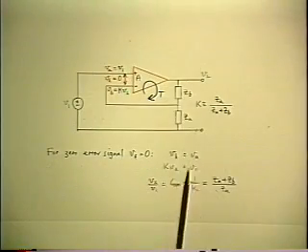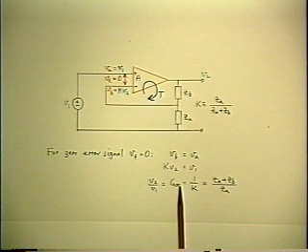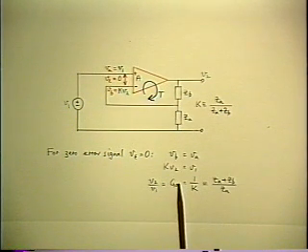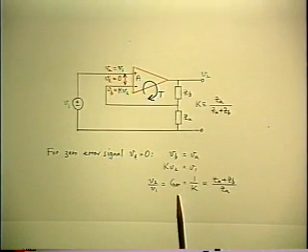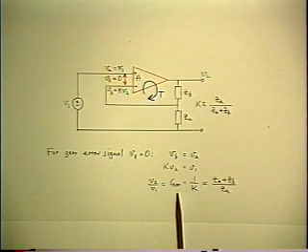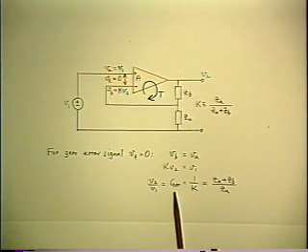And it's the part that usually gets neglected in the design of the system. Because everyone does the part with G infinity, forgetting that it's G infinity and not G, and forgetting to do anything about the D. But you see, ultimately you have to, because D goes away at some high enough frequency. So this is simply a way of emphasizing the fact that the G infinity really is not a brand new quantity. It's the quantity you previously called the gain of the system, and the only modification needed to that is that it's the ideal limiting gain of the system if you had infinite loop gain.